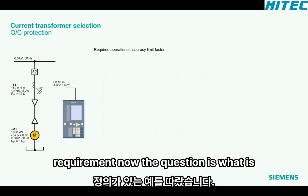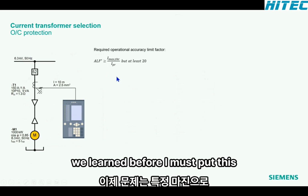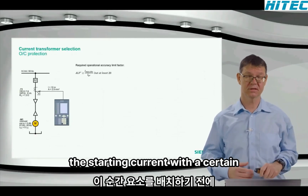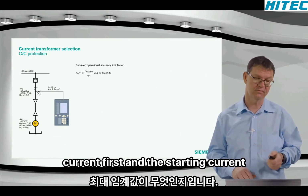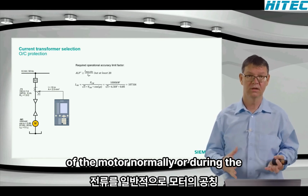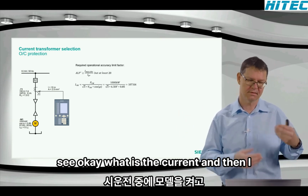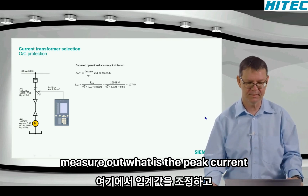Now the question is, what is the maximum threshold we have here? We learned before that I must put this instantaneous element over the peak of the starting current with a certain margin. So I need to have the starting current first, and I can calculate the starting current from the nominal current of the motor normally, or during commissioning, I switch on the motor and see what the current is. Then I can adjust the threshold and measure what the peak current is.